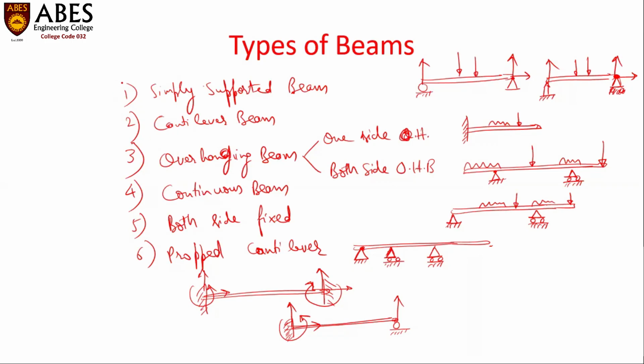So out of these different types of beams, simply supported beam, cantilever beam, and some special or simplified cases of overhanging beam are considered as statically determinate beams because the total number of unknown variables will be either three or less than three. And mathematically, we will have 3 equations to solve. So solving these types of beams is possible.